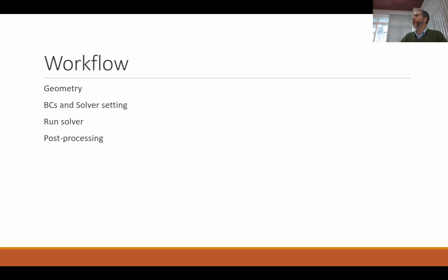But once you have the mesh, you now have the discretized domain. So the next step is that the equations, etc. are set up in the solver that's available there. You have to set up the solver settings as to what options you want to choose in terms of the parameters, geometric as well as numeric. And then you also have to set up the boundary conditions, because boundary conditions will define the problem here, in addition to the domain that you already have now meshed.